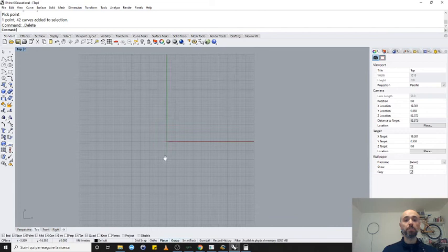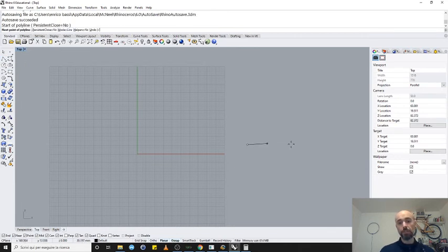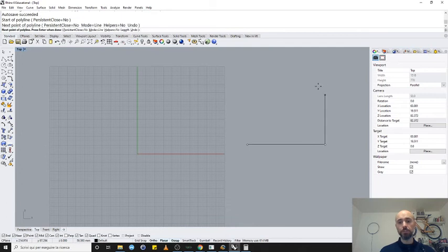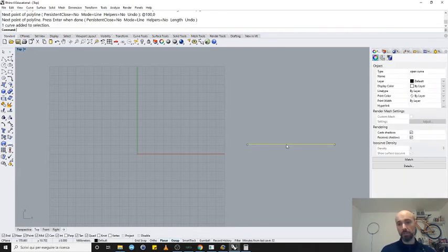So first of all, when you work with the laser cutter and even with milling machines, it's fundamental to be able to draw something precisely. Precisely means not just being sure that things are perpendicular, but also having a precise dimension. We will get into how to do that, but just to give you an example, if I want a 100 millimeters horizontal line, I can do this, and I'm sure that this line is going to be 100 millimeters long.